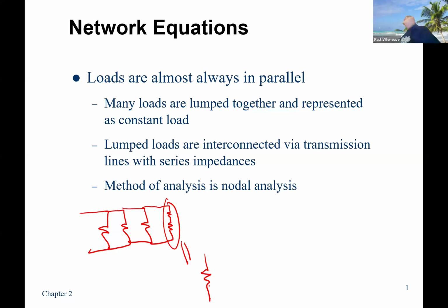Loads, you normally talk about loads as what we call a constant power load, which means the power that is being drawn by that load is the same regardless of the applied voltage. Okay. And that's a fairly easy assumption to make because for the most part, if we're trying to bake bread or something like that, and the oven temperature is too low, then you'll either adjust the temperature up, to put more power into the system, or somebody will have an automatic control system that'll do it. Like on your stove or your refrigerator, they have a temperature monitoring thing, and that'll just keep cycling things on and off until it gets to the desired temperature. So the load is essentially the same.